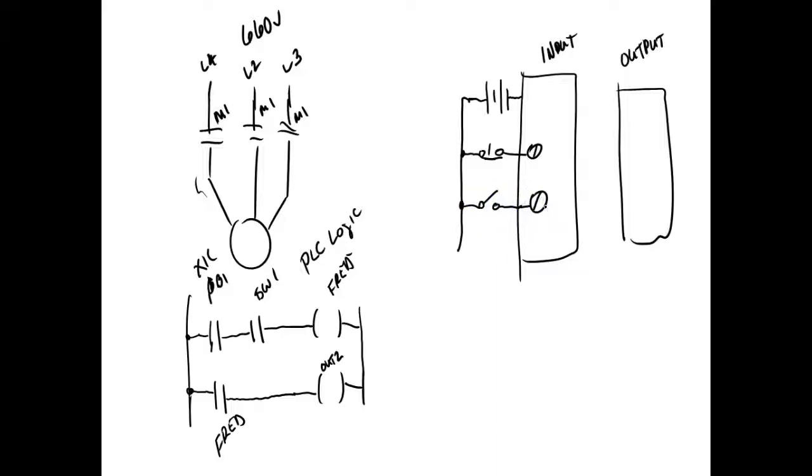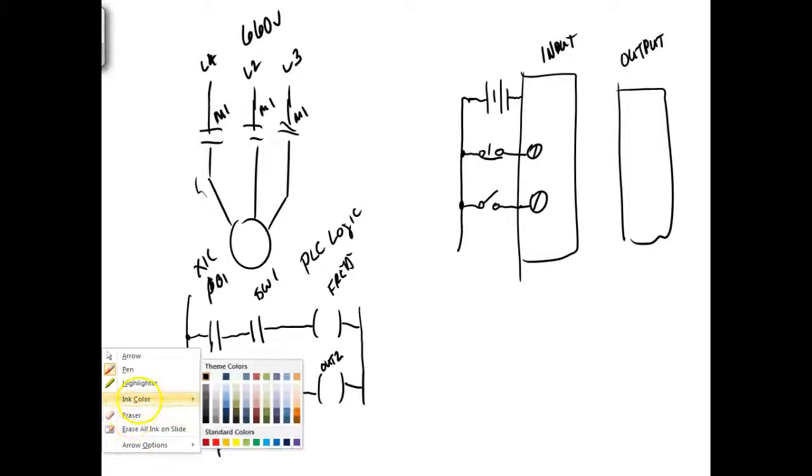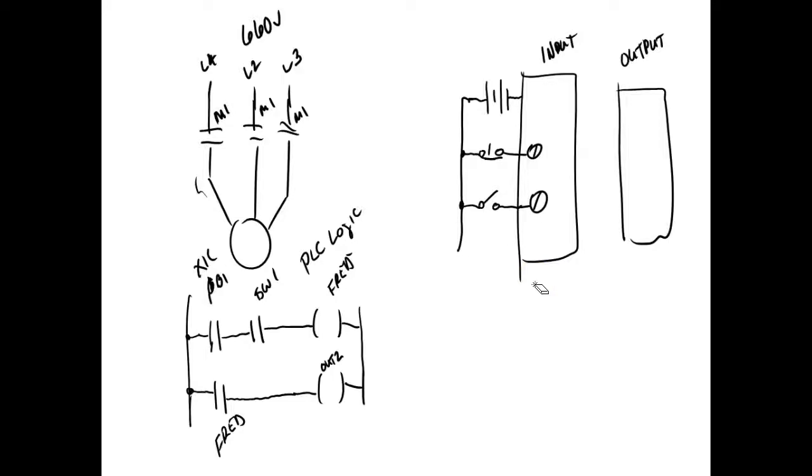Before we get to the top, examine the closed before we get to the top. What do you mean at the top? On the input. We have two basic symbols for a push button, and then we have variations of this. If it's above it like this, even though a lot of times this author does not leave a lot of room, but you see there's a little tiny space, this is a normally open, and then a normally closed is on the bottom.